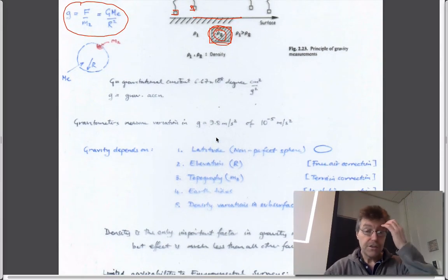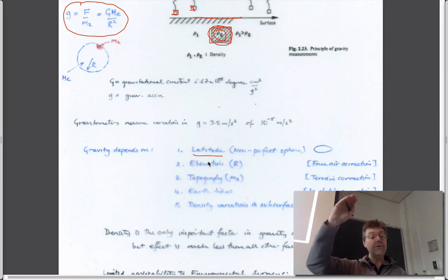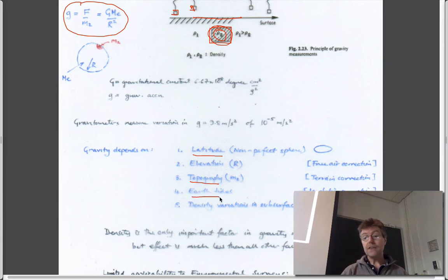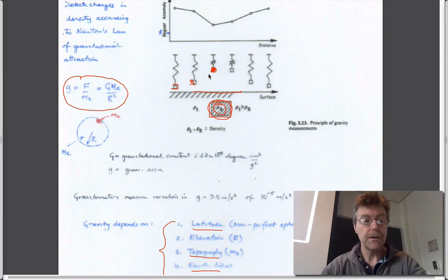The negative, unfortunately, is that all the corrections that you have to apply to be able to correct for the fact that you are in different locations on the globe and therefore have different gravitational attraction, how high you are relative to the center of the Earth, whether you're sitting in Kansas or in the bottom of an incised valley or on the top of Denali, for the fact that there are earth tides that go on, all of these corrections have to be applied to the measurement. And these corrections are often of the same order as the discrepancy, the deviation from the norm of the measurement itself. And so it works, but it's actually kind of fraught with problems. So maybe we should stop talking about that there.